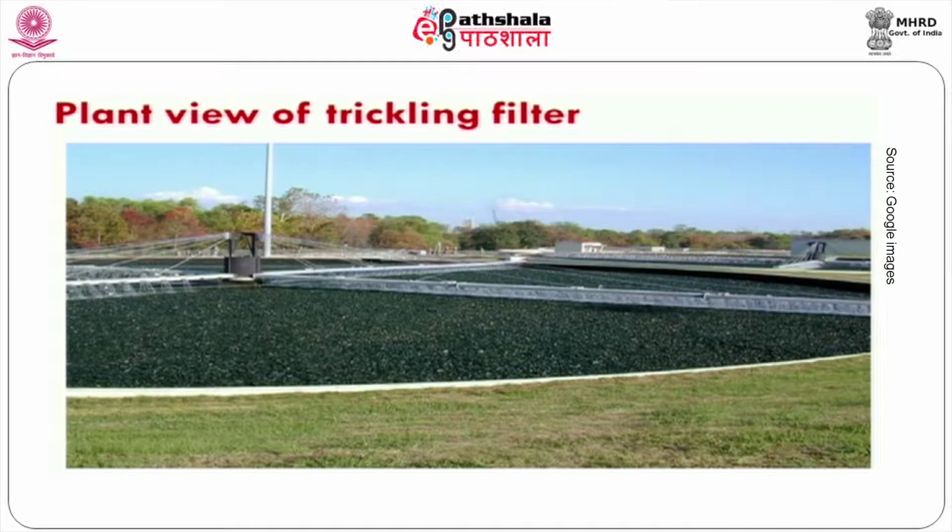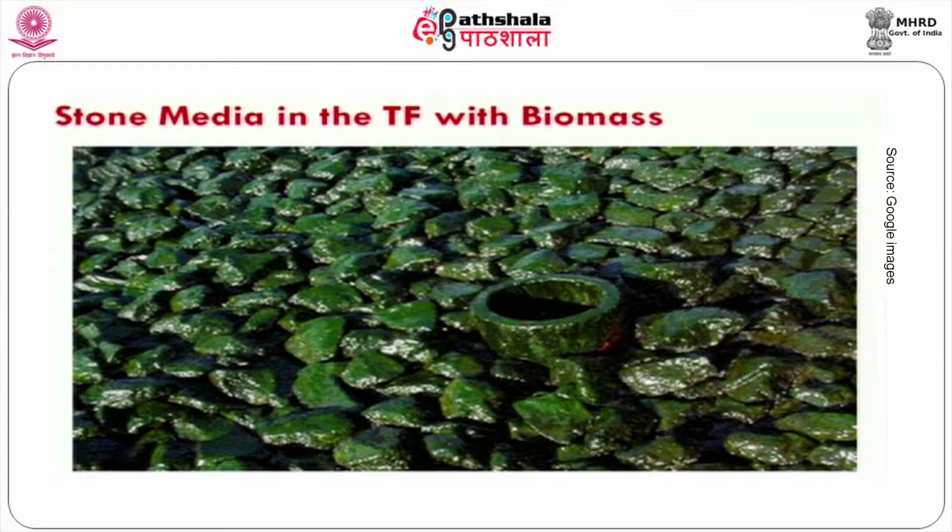So, this is the aerial view of a trickling filter using conventional packing material, a packed bed reactor. This reactor, with stone as the packing media, is a low rate trickling filter. With the help of this trickling filter, we can load up to 420 gram BOD per meter cube per day. We can pack the media up to a maximum height of 2, or even 2.5 meters, if we provide some ventilating ports on the depth of the reactor. So, up to 2.5 meters, the reactor will maintain aerobic conditions. If we want to pack more than 2.5 meters, then we have to modify the media packing.